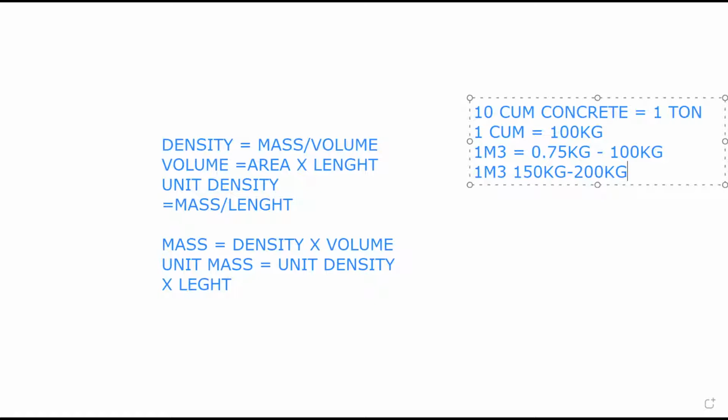So knowledge of that unit weight is the most important parameter. And that's why I told us to go online and try to search it. You'll see that it's all over online. But I also gave us the formula on how to get it. And that formula is diameter square over 162. Diameter square over 162. So you don't need to stress, whatever it is.